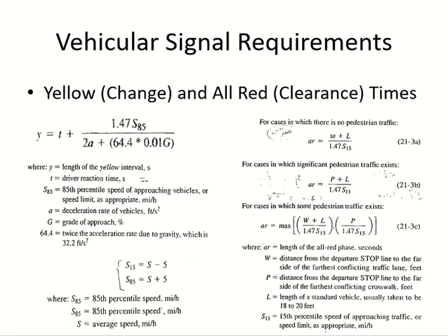And it's the same thing, the same perception reaction time. Do you remember the value? Anyone remembers the value? 1.47. No, it's not. But for signals, it's 1 second. For signals it is 1 second. So T will be 1 second.